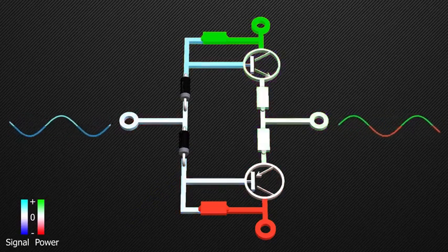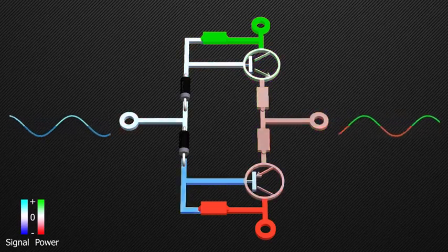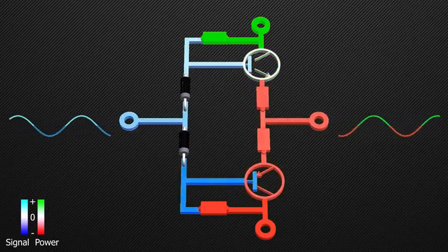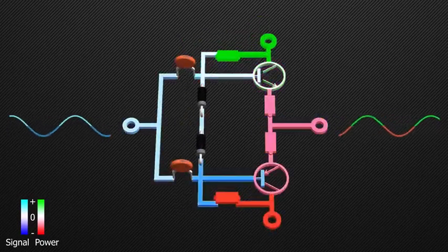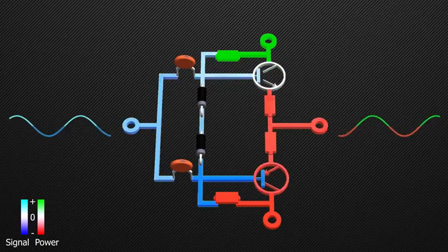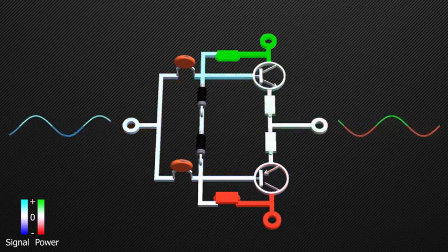Now, any changes at the input will cause the voltage at the other ends of the diodes to change with the bias of 0.7 volts. This is how we bias both the transistors. You can also connect the input signal at other terminals of the diode. We also add capacitors to filter any DC from any direction, and to avoid short-circuiting the diodes. This is how amplifiers of class B and AB work.